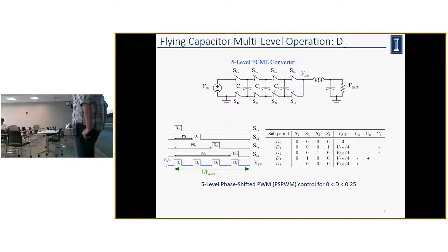Yeah, sure. So, for example, in our case, when one of the caps goes out of balance, every other cap at the same phase will go out of balance in the same direction. But here you have multiple phases. Can you group them into, let's say, an odd phase and an even phase, and then predict, for example, if your C1 is going out of balance, then C3 is also going out of balance in the same direction? So you only read one capacitor voltage and you predict the other one.